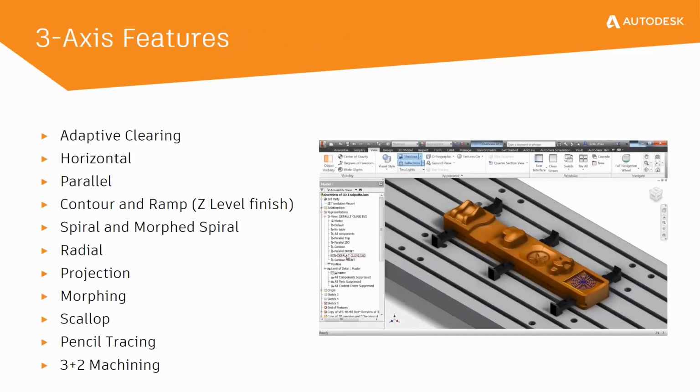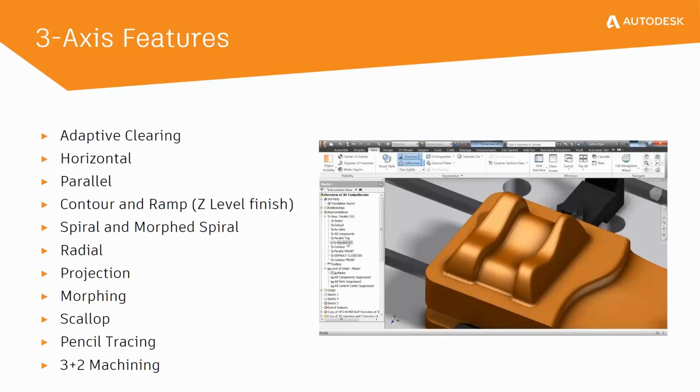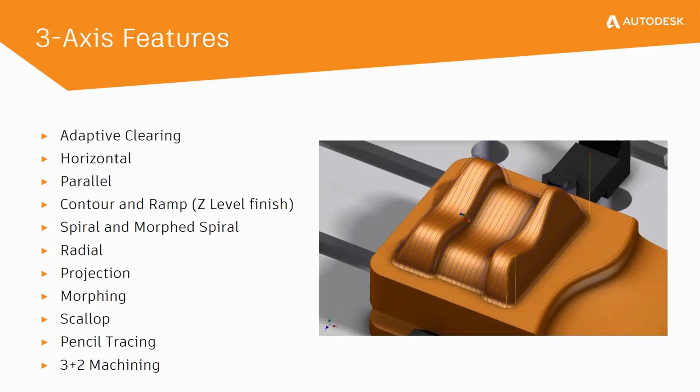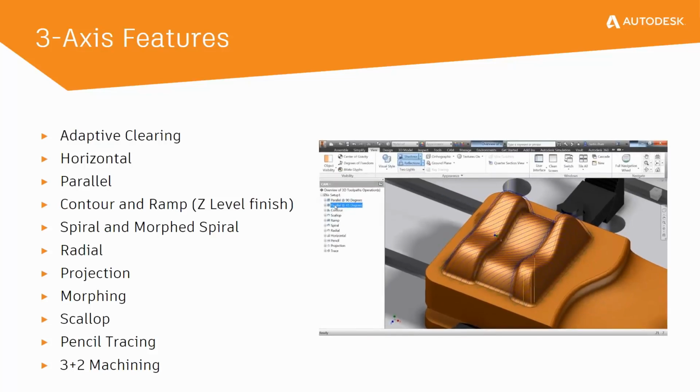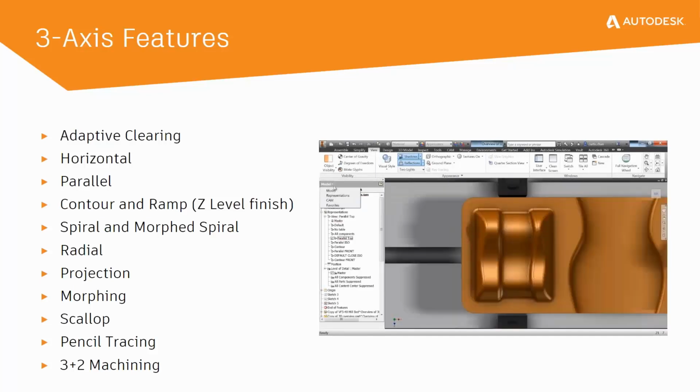Furthermore, there's a range of 3-axis features that aren't available in the 2.5 axis variant, including adaptive clearing for multi-axis strategies, horizontal parallel toolpathing, radial and projection toolpathing, as well as the ability to do 3+2 machining or positional.